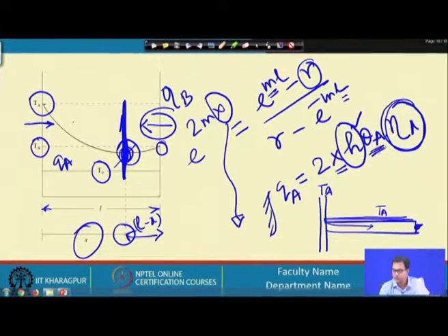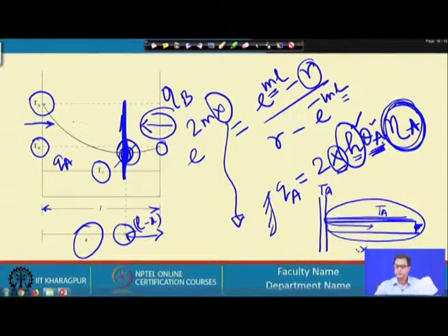We have not written it as theta x or variable length. Here we have put it as theta A, as if this entire fin is at the fin base temperature theta A. So, we are multiplying it with the fin efficiency, eta A, and with the heat transfer coefficient, and this is the length of the fin. By that way we would be able to calculate Q A.